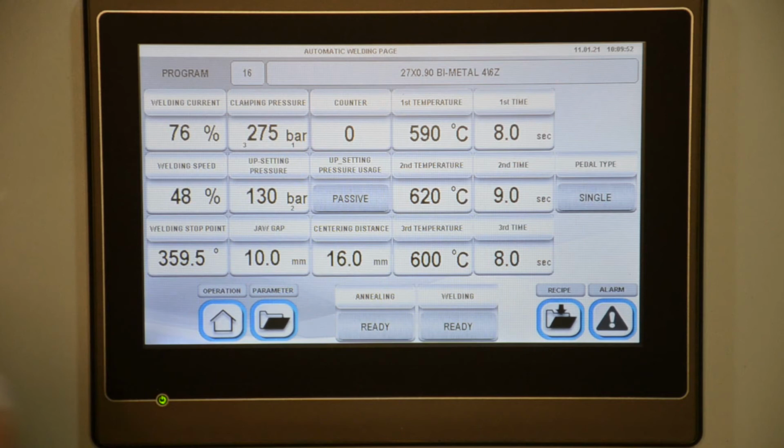During the operation, after you press the start button, there is no upsetting pressure to press the spindle group to the cam. For the bigger size blades which need more than 150 bars of upsetting pressure, there is an option to make a first upsetting pressure which is lower than the upsetting pressure set value in the program. This keeps the spindle always following the cam to make your operation more secure.